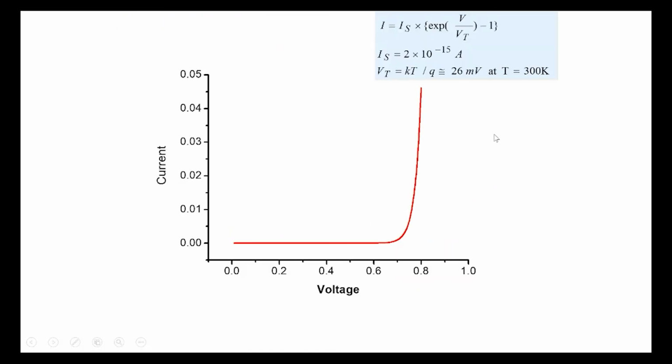Okay, so let's illustrate that. In this case, note that we've taken a diode characteristic which is in the range of 0 to 50 milliamperes here. So why have we taken that? Well, suppose you analyze your circuit which contains a diode and you know that your currents are somewhere in the range of tens of milliamperes. It could be 20, 30, 40, somewhere around that. Then this kind of a scale is meaningful. In this case, we will approximate it like this here.